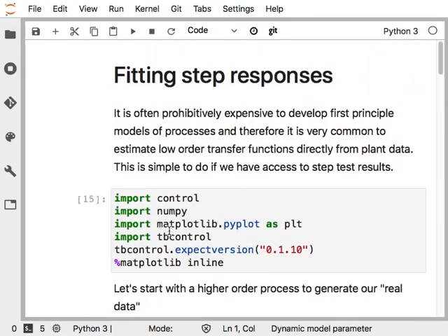But partly because of all these other things that I've just been talking about, the noise and the problems with doing pure step tests are not used very frequently in the industry any longer. Instead, people will use a completely different strategy, which is based on linear regression. And I'm going to walk you through the logic of that in today's lecture. So this is an important technique. It's important for you right now, just because it is something that you can do to optimize the parameters of your model for the project.